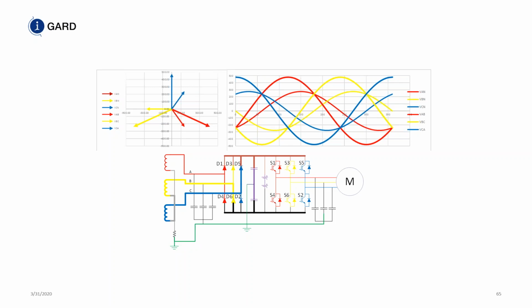But if you put a fault on your system with an ungrounded system, where the fault is, and if you measure that current, that will be your capacitive charging current of what you have connected to the load at that particular time. So it's only going to measure the capacitive current of the connected load at that time.